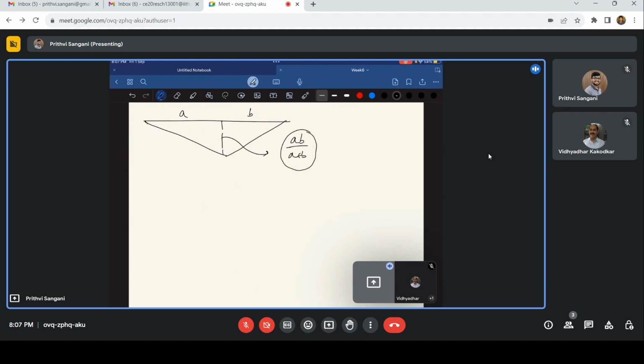So this ordinate should be maximum. When it is maximum, we can say that that gives us the maximum bending moment, right? So it is maximum when A equal to B equal to A plus B by 2, or that is nothing but the span by 2. So the maximum bending moment always occurs at the midspan. So at this span, when this is the midspan, the ordinate is AB by L.